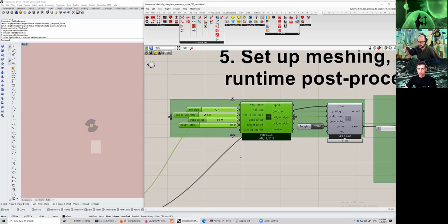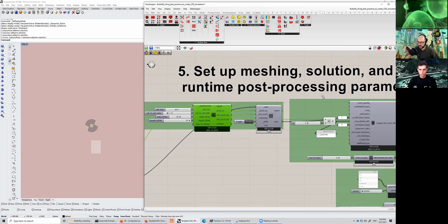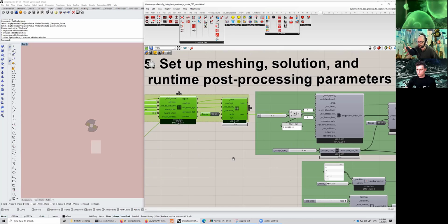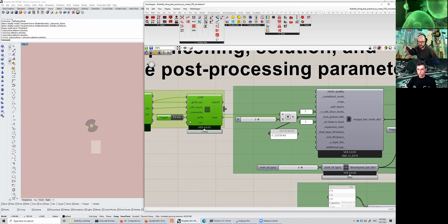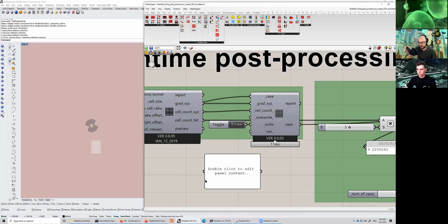So with these options, this sort of best practice and logical options, you create this gradient mesh, right? And this is what these components do. I will go later and show you how this happens in action. After we're done with that, this also gives us the total cell count here, which is interesting. It's good to keep in mind, right? So this is the total cell count of our background mesh. This doesn't include any geometry yet. Our building, our Agora building, is not meshed yet. And we have 450,000 cells. That's okay. For urban studies outwards, it makes sense with the computers we have today, right?